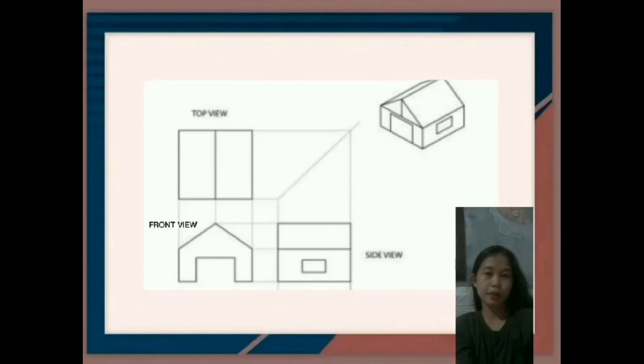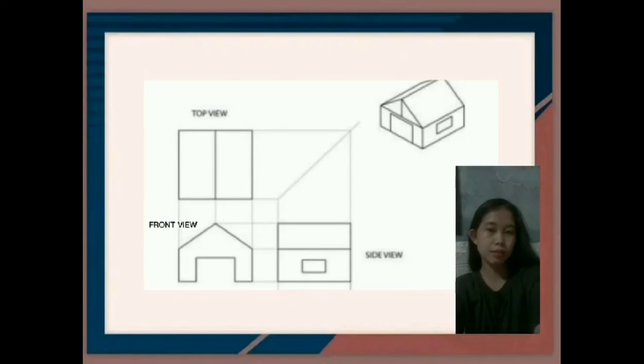An orthographic drawing is a drawing that shows the top view, front view, and the right side view of the three-dimensional figures. The top view is projected directly above the front view, and the front view and the right side view is also lined up with each other. The height, width, length of the object must remain the same from view to view. But the important thing to remember in orthographic sketching is the alignment of the views.